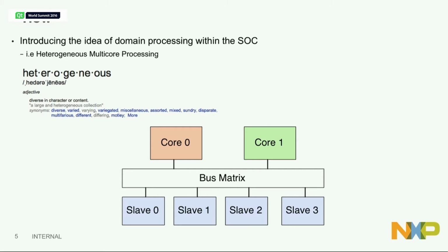But I'll go to the punchline first. It's a challenge. Every time we've introduced this to a customer, we have one design team that does Linux. Where's my shell? Most Linux guys don't even know about debug tools. DS5, what's that? We don't even use it, just shell. Now if you put an M4 in there, there is no shell. You have to use debug tools. It's a little bit different thinking than the Linux guys.